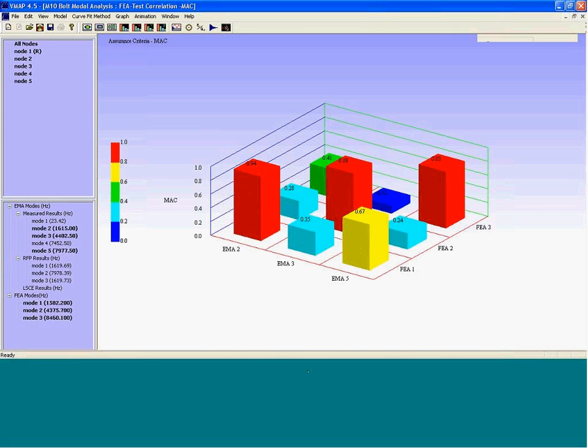Now I want to move on to the next demo where we want to take data. What we looked at was one experiment. So now if I want to take say 2 or 3 experiments and compare the data so that when I look at the FRF, I can see if there is a significant separation between the two, or I can perform curve fitting and see if there is a significant difference in the other parameters, say damping, between the test and the FEM. Given that, if there is a significant variation, this could set a test procedure for separating the good parts from the bad parts.